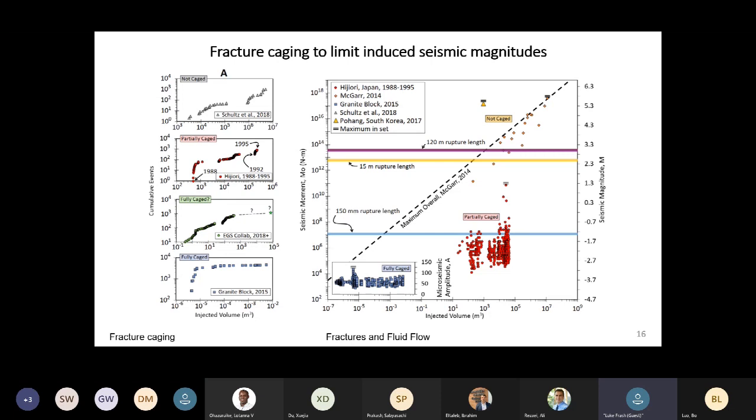And if you look at hydraulic fracture propagation models, ultimately it very much comes down to the volumes. And the pressure is just something that has to happen to get there, but it's not really the driving mechanism for continuing propagation. Not in my experience.